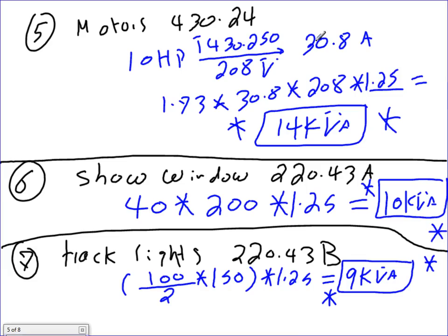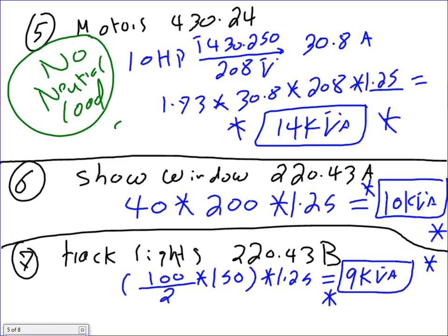All right, let's go to the motors. Is the motor 3-phase that we have? Do I need to worry about neutral here? The same thing. No neutral load here. And I'm going to write it here. And why? 3-phase balanced. If anybody wants to know why, it's 3-phase balanced. I don't have neutral.